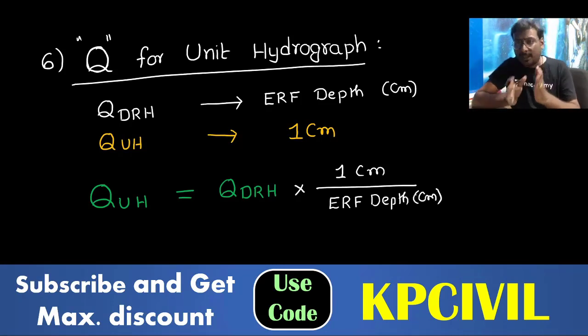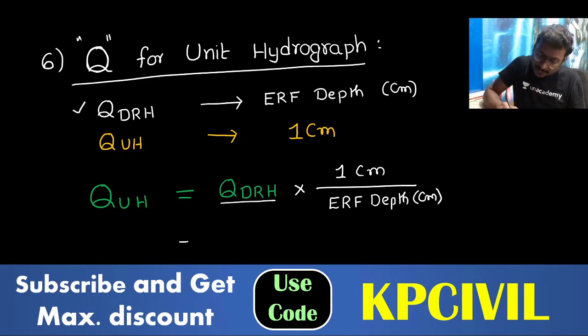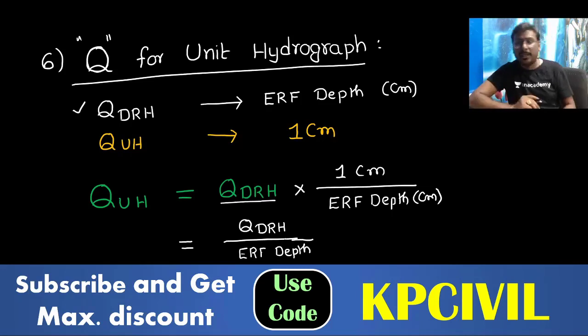Effective rainfall depth of the storm you are analyzing, which is resulting in this QDRH. So in simple we can write it like this: QUH is equal to QDRH by effective rainfall depth. That is the unit hydrograph discharge values.